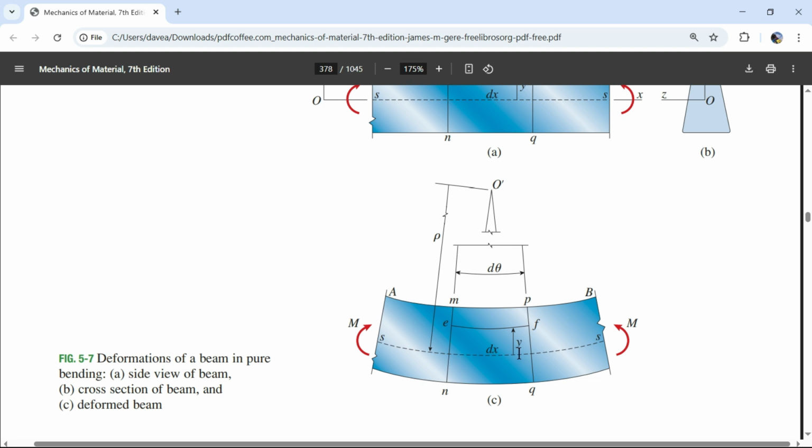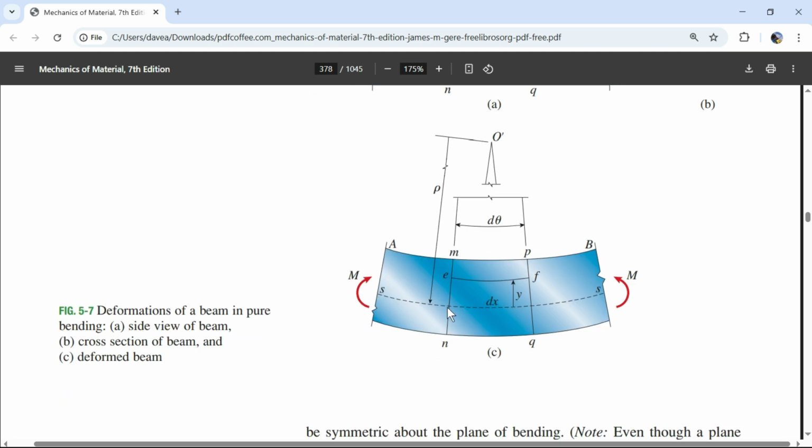That also happens in chapter 9: even though moments cause a lot of deflection, the deflections are still very small, especially within the linear range. Things don't move very much. They can move a little bit noticeably with bending, but those deflections are small enough that we just assume the x-axis follows this line in general. Even though it's 90 degrees, it's tangent to this point at that cross-section.